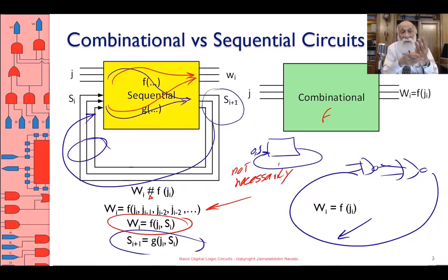That means my circuit has 8 states. And each state is what has been accumulated from the past. If I have 10 lines, I have up to 1024 different things that my circuit can remember, potentially.